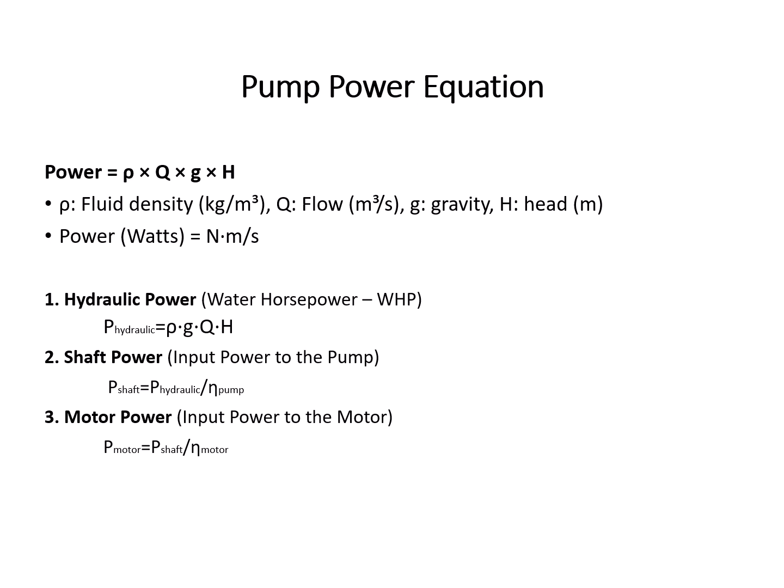So it is simply the hydraulic power, which is the power that should be provided by the pump, but it will not provide this calculated hydraulic power because of some losses, and we divide it by the efficiency because it is not 100% efficiency.